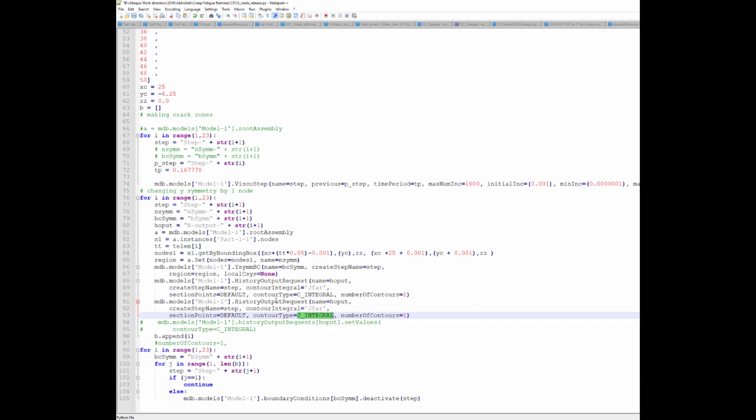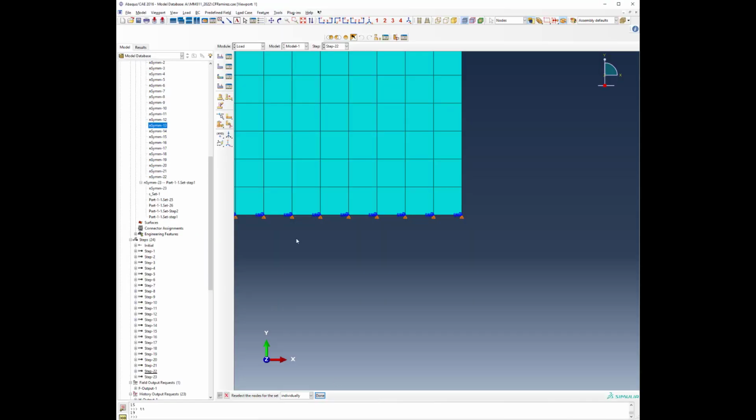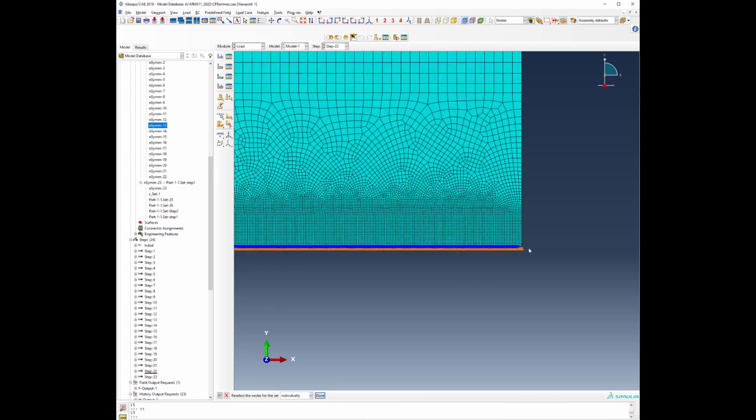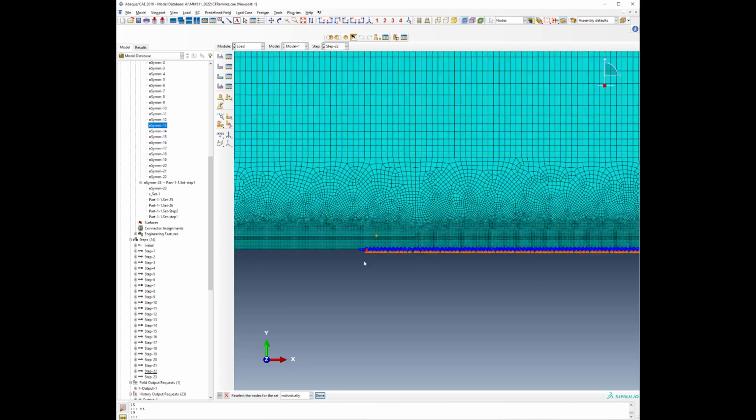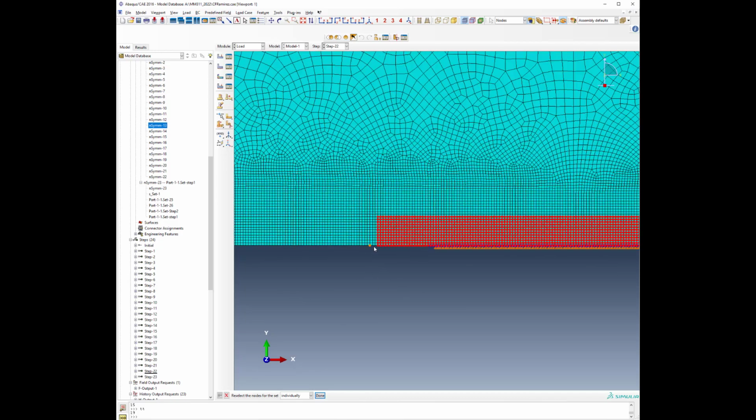But we will be doing it differently because this is not working properly, and then we deactivate the boundary condition which is created in a certain node set, and then for the rest of the node sets it is deactivated. So that I will show you here. So what happens is that when you release the node, so in one of the steps, let us say you said that this many nodes are under symmetry condition, so that is the ligament, and then you release one node.